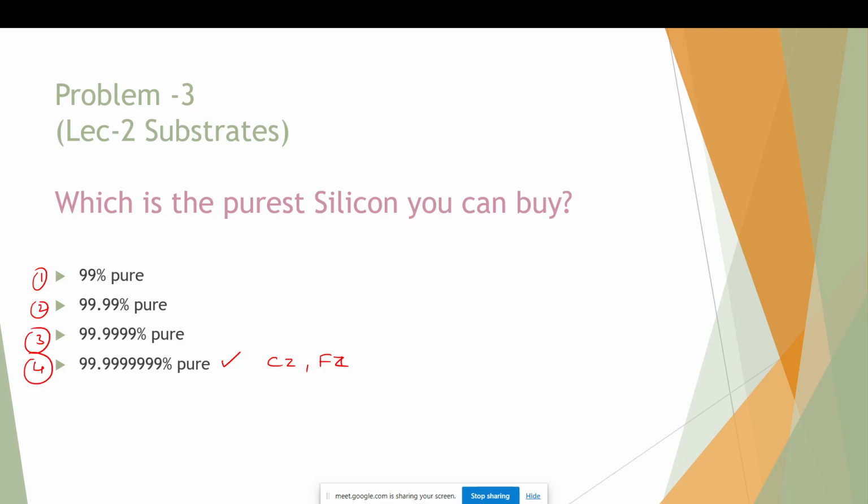Instead of having silicon in the melt form, I gave you a polycrystalline silicon ingot. Ingot is just a shape, right, at the end of the day. So I give you a polycrystalline silicon ingot. You can melt it, you can solidify it, you can partially melt it, do whatever, and get wafers out of it. So which processes are used? That is the question.